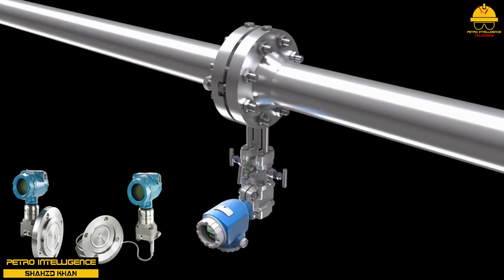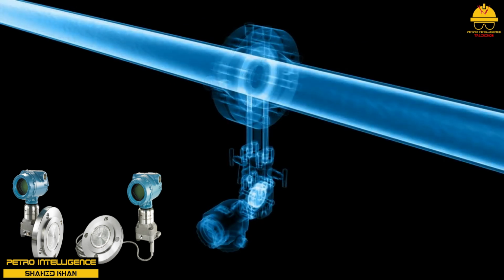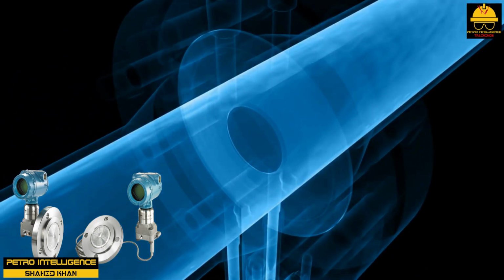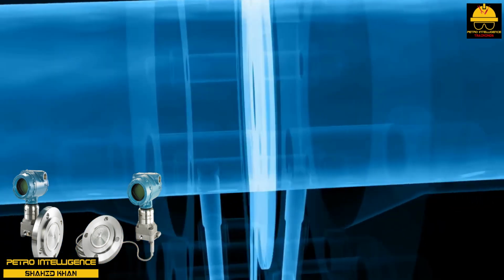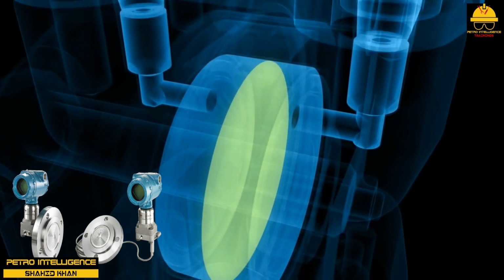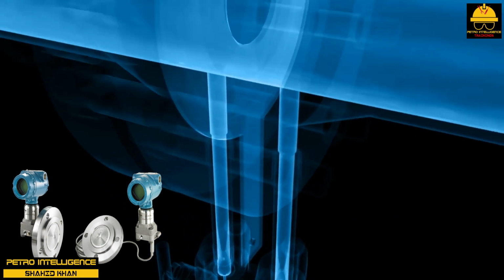Transmitters. DP cell transmitters can be found in two basic designs, pneumatic and electronic. Controllers are typically mounted between 400 feet closed loop and 1000 feet open loop from the transmitter. The signal from an electronic transmitter is proportional to the pressure difference between the high-pressure leg and the low-pressure leg. Standard output signals are 4 to 20 milliamps, 10 to 50 milliamps, and 1 to 5 volts. The 10 to 50 milliamps transmitter is used because it has a higher tolerance to outside interference than does the 4 to 20 milliamps transmitter.